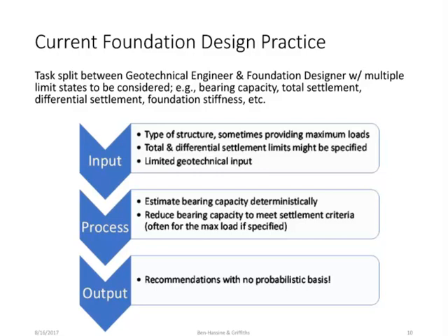I want to talk about the current foundation design practice, what happens currently. The task is split between the geotechnical engineer and the structural or foundation designer. They start with some input. Typically, the geotech engineer is given quite limited information: maybe the type of structure, sometimes the maximum load, and sometimes the client specifies limits on settlement, differential or total. And we give some geotechnical parameters, like those from a geotechnical investigation.